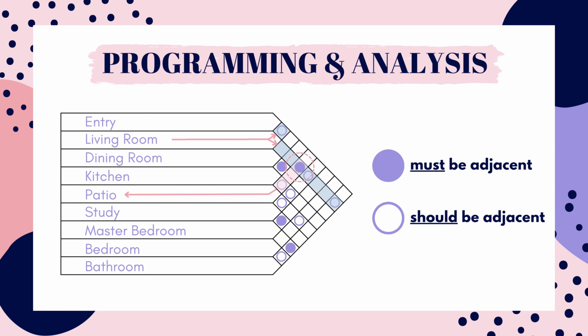So how do you read this thing? Well, first locate the living room. Where each angle line is, you follow that diagonally in both directions, so up and down. These are highlighted in blue. The filled circles show mandatory adjacency, and the open circles show secondary adjacencies. You'll find the one solid circle in the blue, and then you just follow that diagonal down, which is highlighted in pink, and that leads you to your answer, patio.